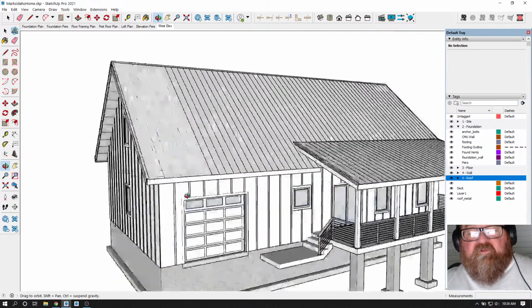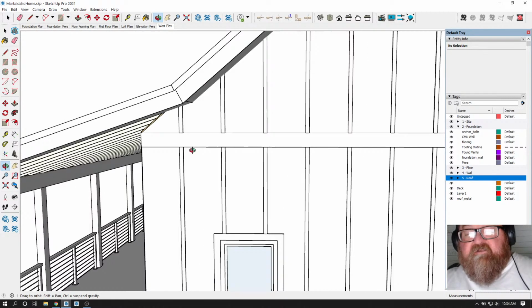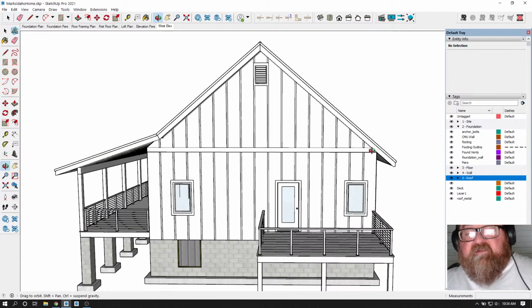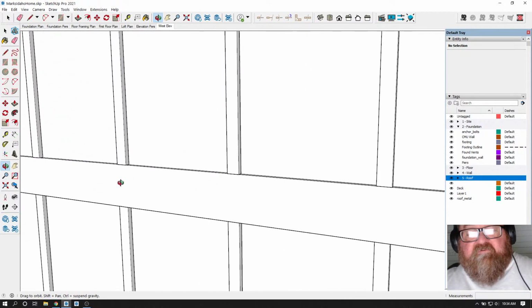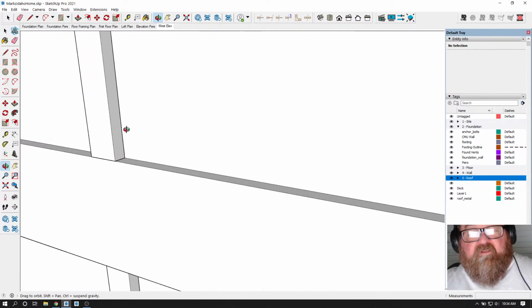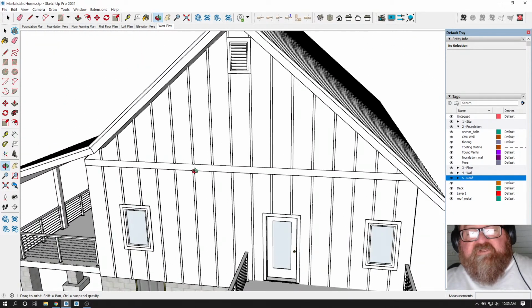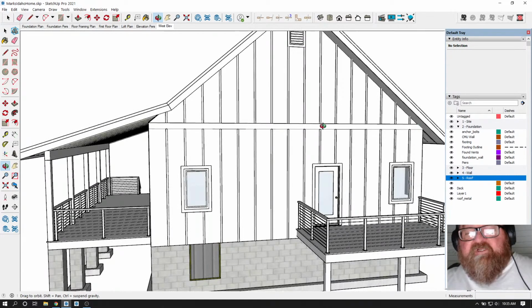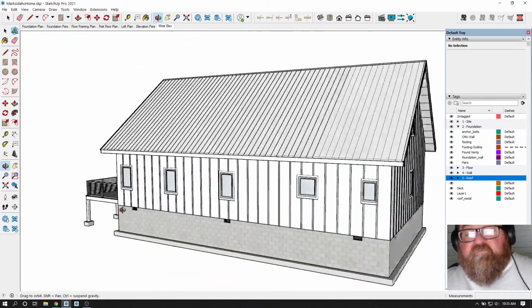Now, the more expensive way to do it is to put a band like this at the top and the bottom. But the problem with that is you're adding the expense and the labor of the band, the trim band, and your Z flashing is bigger and more expensive, because what you have to do then is have a Z flashing that goes behind this siding, comes out over this and down the face of this a little bit. So you still have to have the Z flashing. It's just bigger and more expensive. And of course you've got the labor and material of installing the trim band. So I'm going to present both ways to him.